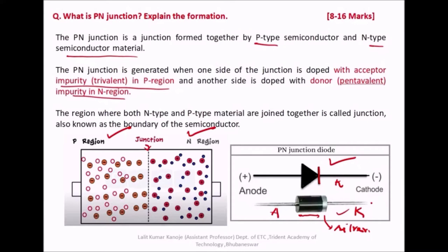As we discussed already, a resistor is a non-polar device. Can somebody tell me, is a diode a polar device or non-polar device? Of course it is a polar device because it has positive polarity as well as negative polarity. So it is a 100% polar device. So you have to take care about this when you connect it in the circuit. You need to check which one is the positive terminal, which one is the negative terminal whenever you connect this particular device in a circuit.